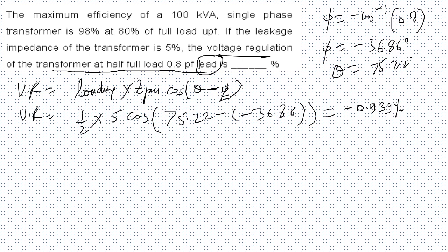So this is how you can solve a question related to voltage regulation, where the efficiency is also given to you. And be careful whether it is at lead or lag, and what the loading is. According to the loading, your voltage regulation may be different.